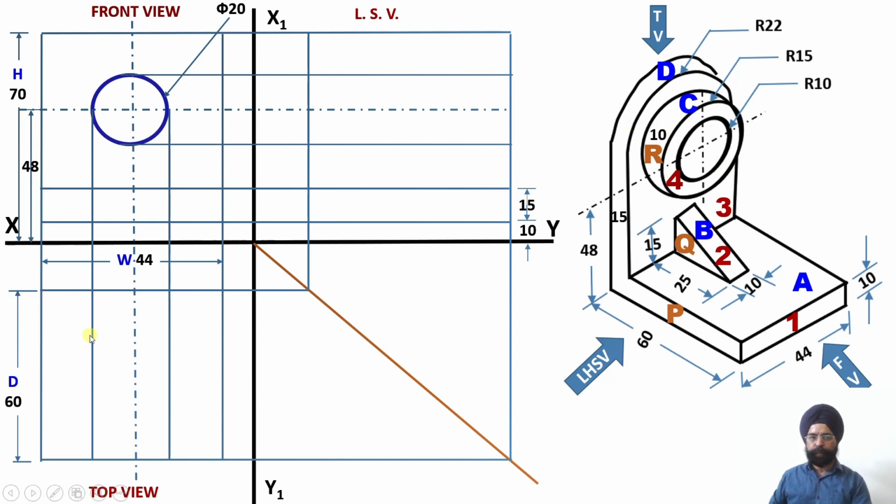Wherever this portion will be there, I have to draw a dotted line corresponding to this hole. Similarly, as you look at this particular solid from the left side, once again, whatever portion will be there corresponding to this web thickness, again I am going to get two dotted lines over here corresponding to these two projection lines.